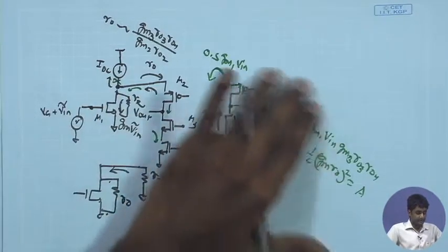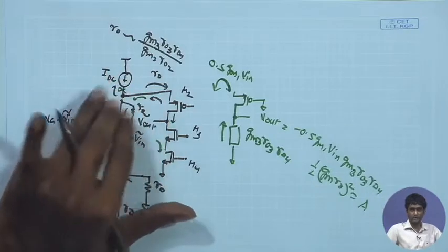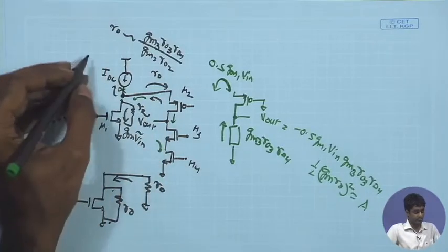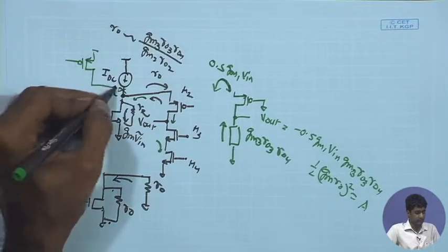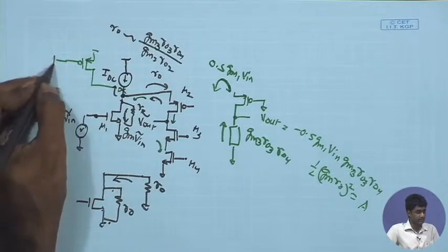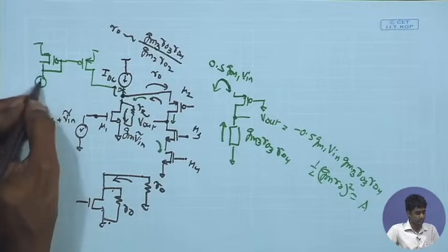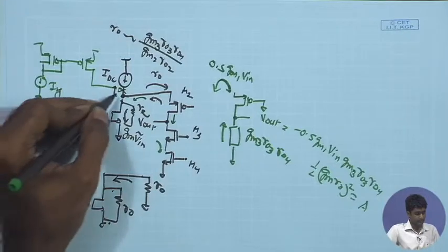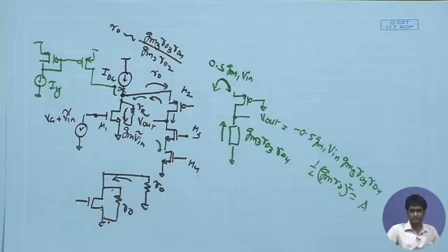So, what is the difference in this signal analysis if I replace it by a non-ideal current source realized with the help of just a simple PMOS transistor supposed to supply some fixed current? So, I can realize it with the help of a PMOS transistor, and this is in turn biased with some reference branch that we can construct, right. So, is there any difference we are going to encounter in the resulting small signal analysis? At what stage are we going to have the difference?